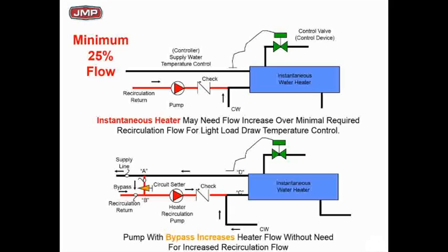So if you had one shower, this is a 100 GPM water heater, one shower pulling in 1.5 GPM maybe, and nobody else in the building, you got 1.5 GPM of cold water coming in the black line, going to the supply, and you got a steam control valve that's maybe 4 inches, sized for 100 GPM, and there's only 1.5 GPM there, and that water's cold.